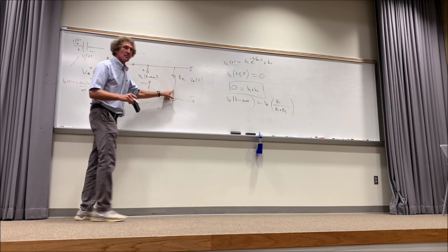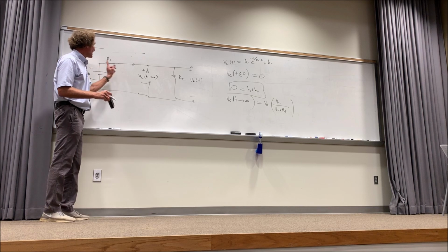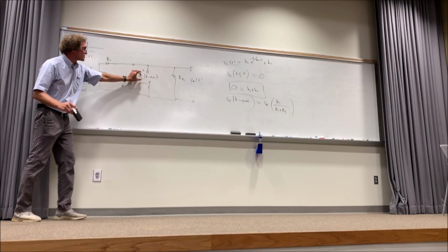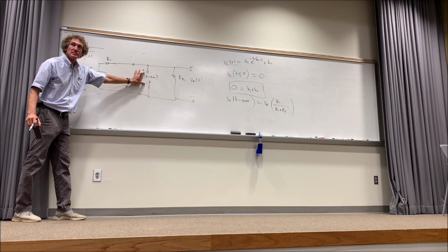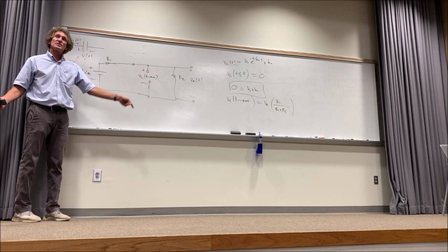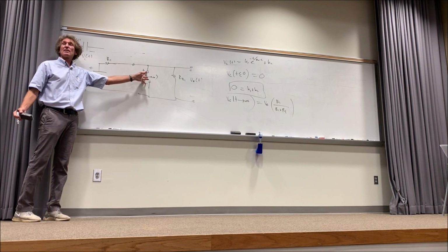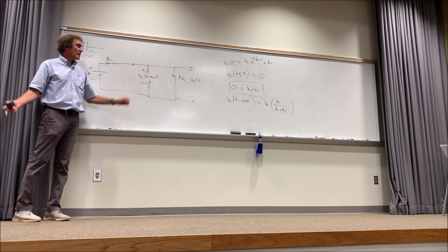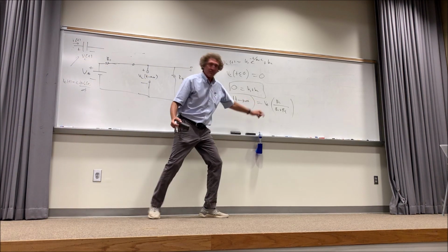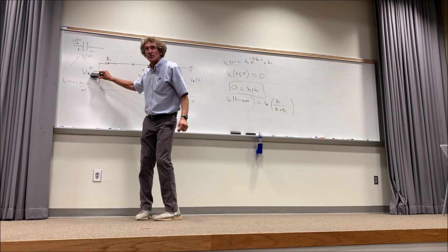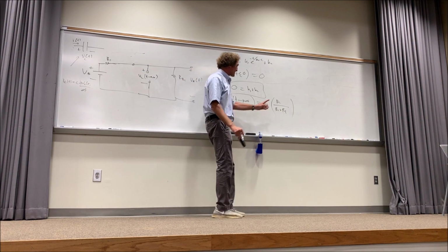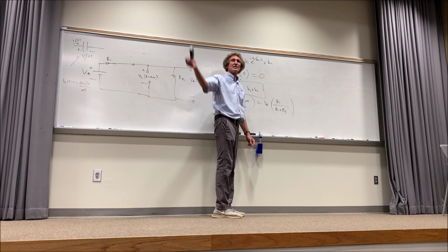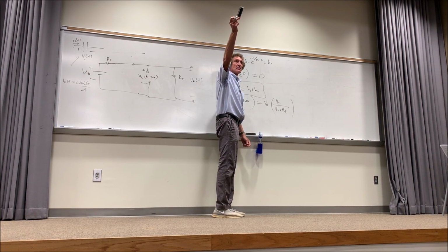This is R2. This is R1, right? Aren't these two in series? Yes. Isn't the voltage across that resistor the voltage across that capacitor? So I just want the voltage across the resistor as t goes to infinity. That capacitor looks like an open circuit. Follow me? Okay, so what does that say right there? That's V naught, the source voltage, times R2 over R2 plus R1. That's all it says. Can you all read my writing back, you guys? Far back? It's kind of hard.